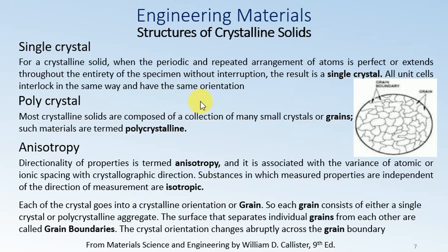You see there are boundaries or separations that separate one grain from the other grain. If one single grain extended throughout this figure, for the completeness of this circle, then this would become a single crystal. But now we have different grains of different sizes and different orientations. So now this material has become a polycrystal.